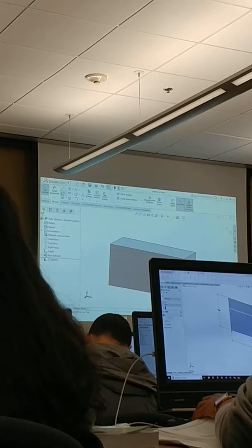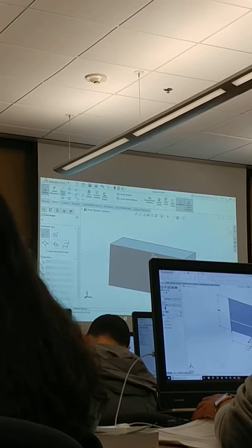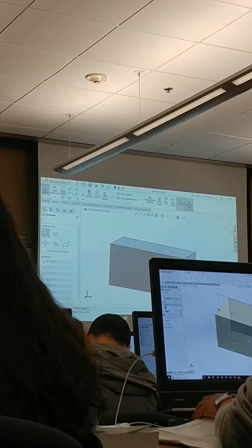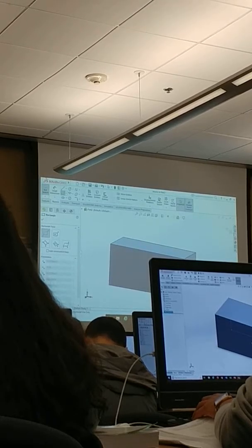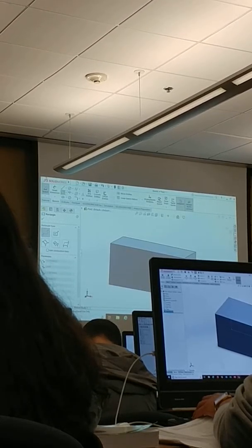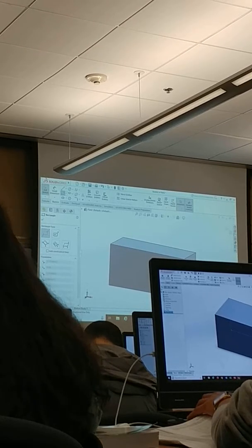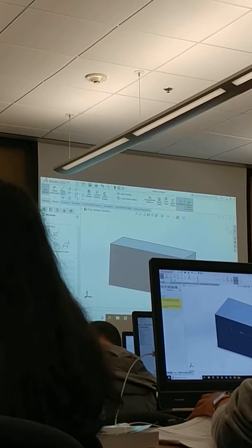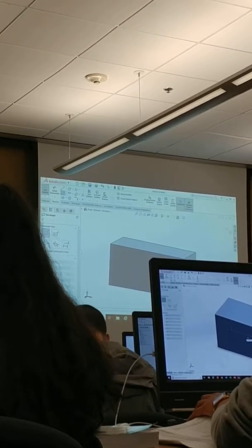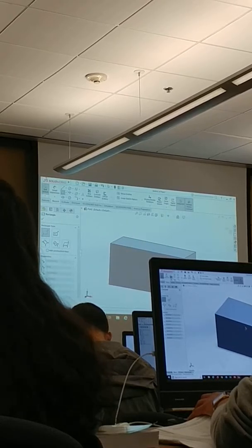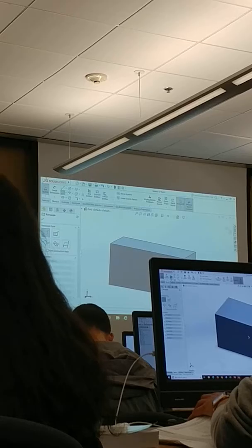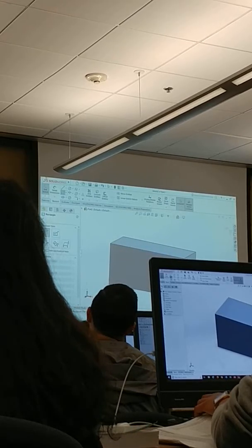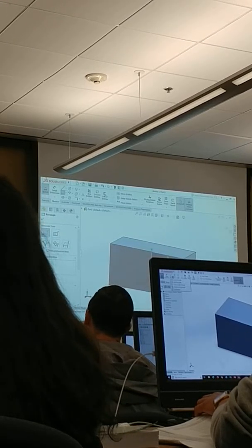So I'm going to use this again, the square. I'm going to just click somewhere right here, and then I'm going to see how it kind of wants to snap on its own. It kind of has an idea of, oh, you want to attach it to this line here. You'll see that little yellow box next to my mouse. That's called a relation, and we're going to talk about that. It's going to be on the test too. Relations are how you balance some kind of function. So the function is saying this is coincident to a line. So say yeah, that's good.